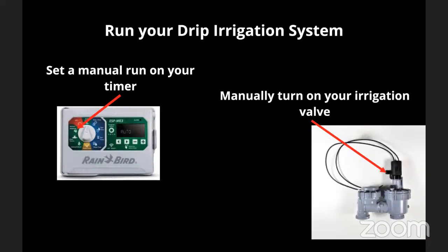And then if that's the case, it's really easy. You can just cut the line there, and with one of those fittings that has the barb on both sides, you just push it back together.